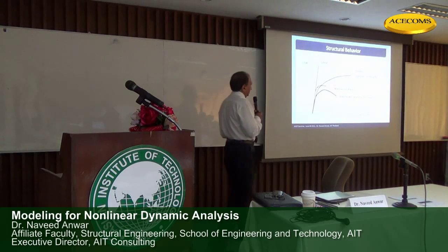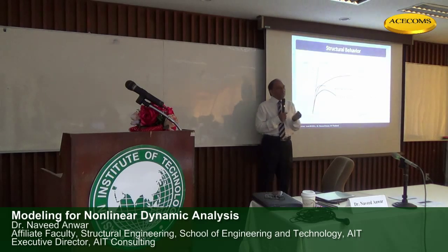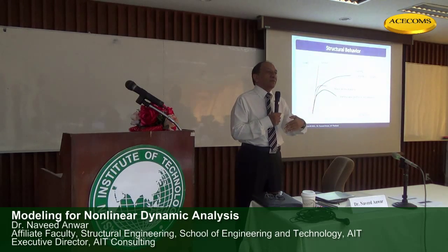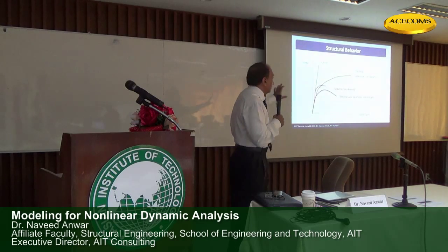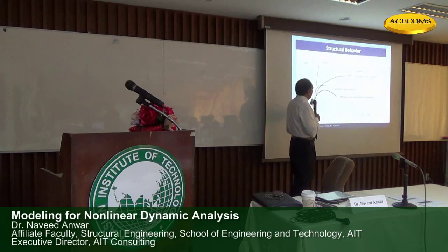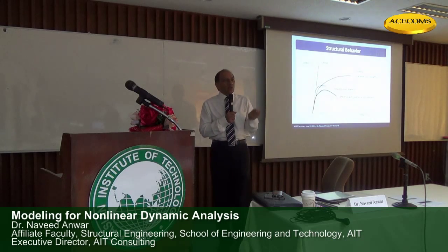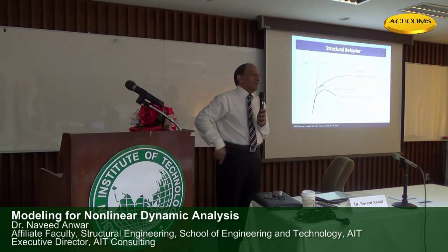For the total structure, this is the linear response that you normally think. This is the material nonlinearity alone. This is material and geometric, and this is the buckling geometric nonlinearity. So local buckling is not part of the total structure. That is a member level thing. A member will buckle, and it will become a geometric nonlinearity for the whole structure. So this way we can see that, okay, we need to include these nonlinearities into our model and analysis. Two things: modeling nonlinearity and doing nonlinear analysis are two separate things. You can run a nonlinear analysis on a linear model.